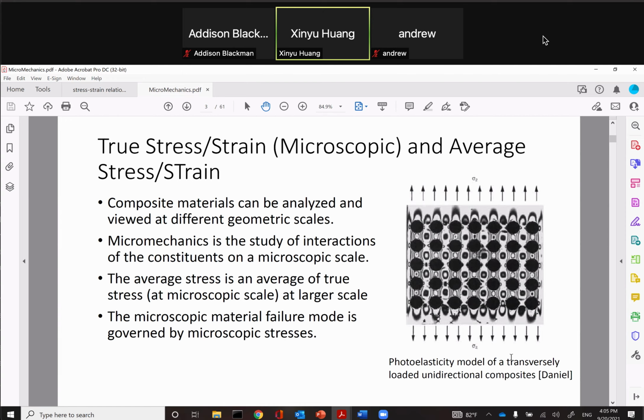Now, when you talk about stress at a bigger scale, you often say this lamina is under 300 megapascal tensile stress, maybe. Then you zoom into a smaller scale, and that 300 megapascal is not uniformly distributed. If the material is not homogeneous, you have all kinds of stress concentration at the corner of the rounds. So frequently the macro scale stress is an average. At a smaller scale, things get really non-uniform. You would call this material inhomogeneous because from point to point there are differences.